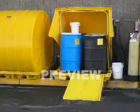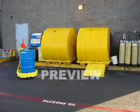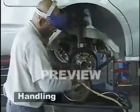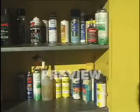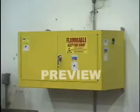If your plant does not have a drum storage room, drums should be stored in a safety cabinet. They are available in sizes to hold drums vertically and horizontally. The handling stage is workstation operations, when you're using flammable liquids as you work. There are many workstation cans and tanks from which to choose. Liquids should be stored in safety cabinets near the workstation.